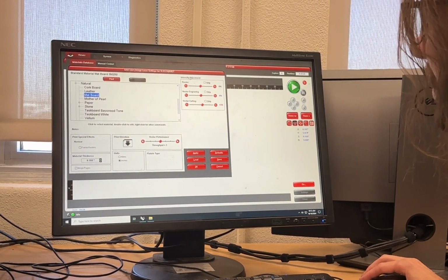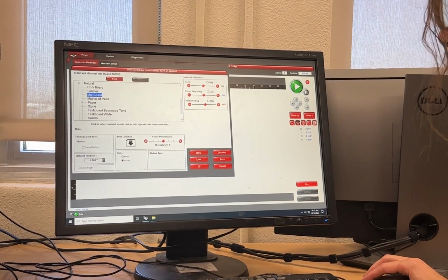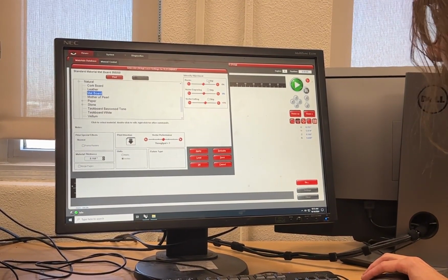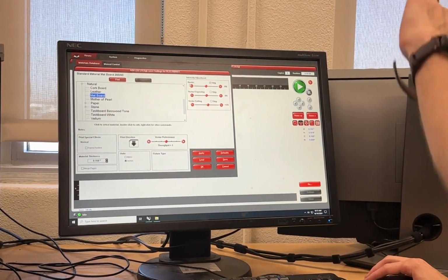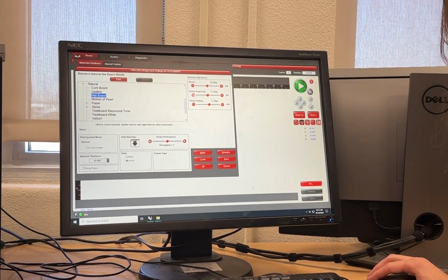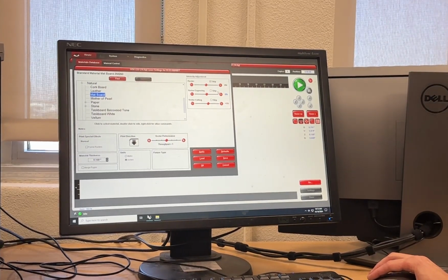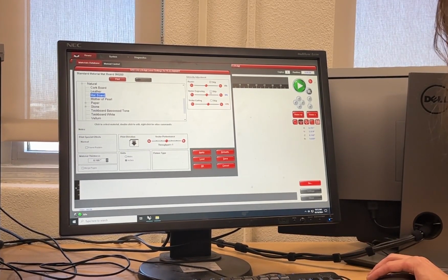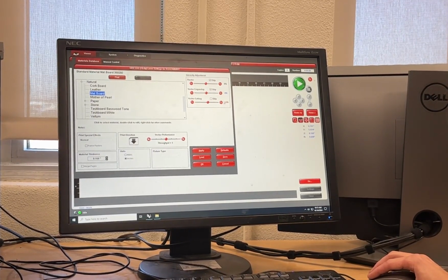You'll see that there's, at least in the materials database tab, a couple of options. Obviously, raster, I would always skip. And you'll notice that the text itself is in the color black, and that's because the color black controls the raster layer. You'll notice that vector engraving, I want to skip because it's in blue. I don't have any blue lines, so I can skip that too. Now, vector cutting, good thing it's in red because, well, that's red.